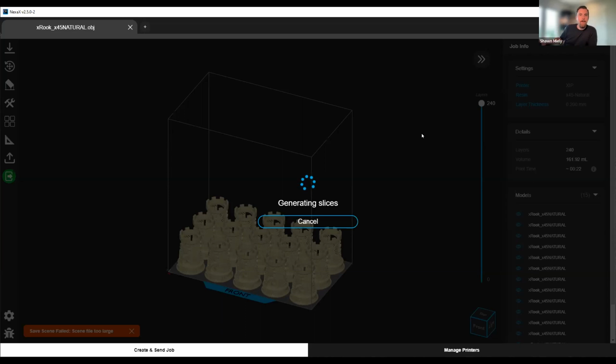Yeah. Okay. Probably just best to use that full build plate, because what people might not know with this technology, which is an mSLA type technology, is that you don't get penalized for additional usage of the build plate. If you compare it to an FDM 3D printer, where the print head has to print and then move over and then print this part, everything on the build plate on that layer is being printed at the same time with the light being flashed on it.